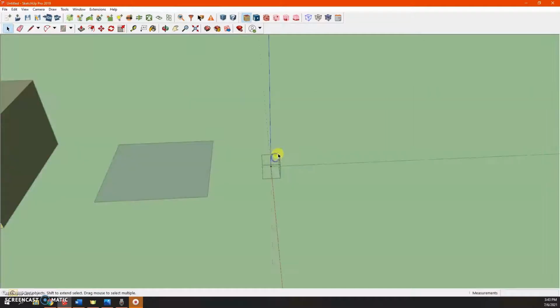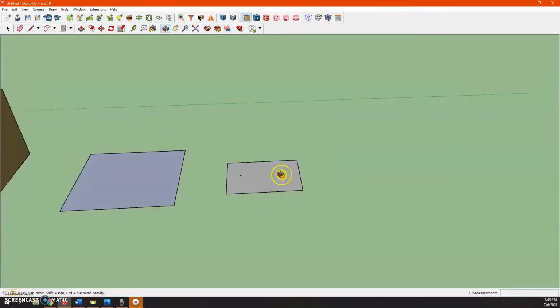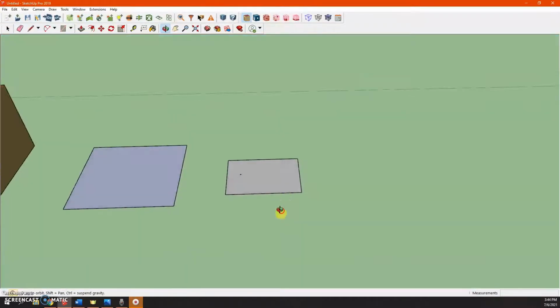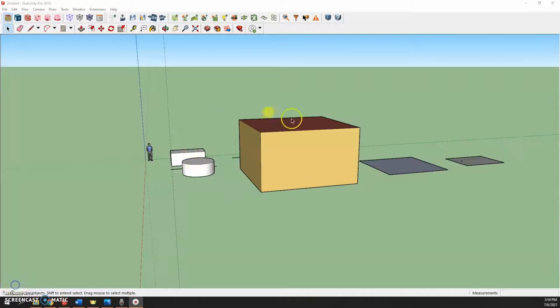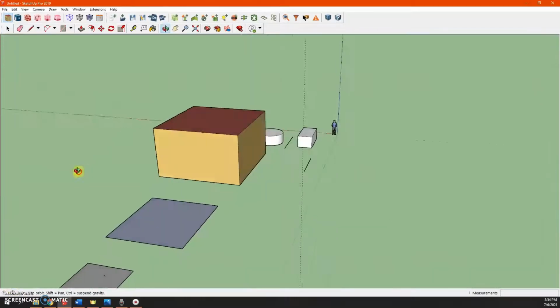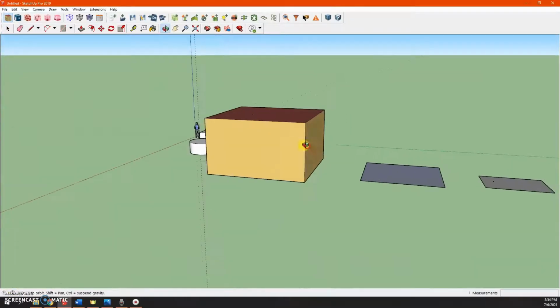One thing to note too for OpenStudio geometries, the darker side will be the external face. So as you can see in the floor, that's the darker side, and then the lighter side will be the internal side. And now I'll talk about some other types of geometries, and before I do that, I cannot emphasize this enough.